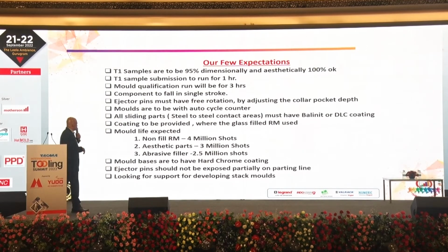Molds have to be fitted with an auto cycle counter, because otherwise you cannot know when you want to replace the mold, since we expect a certain life.